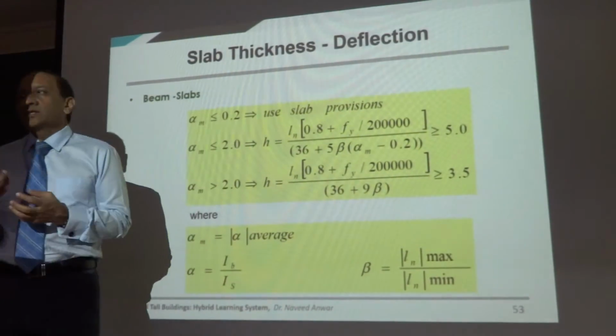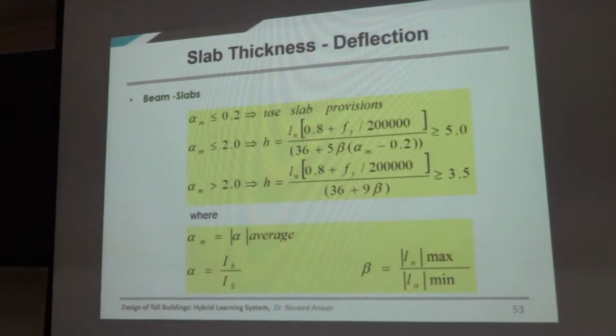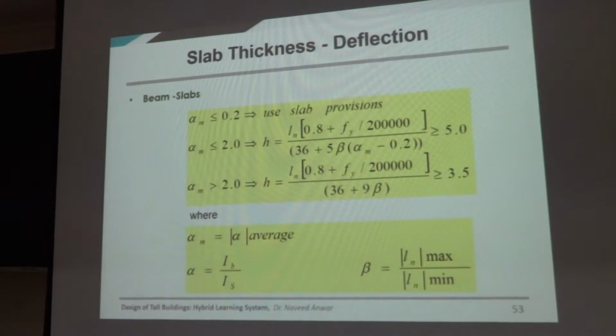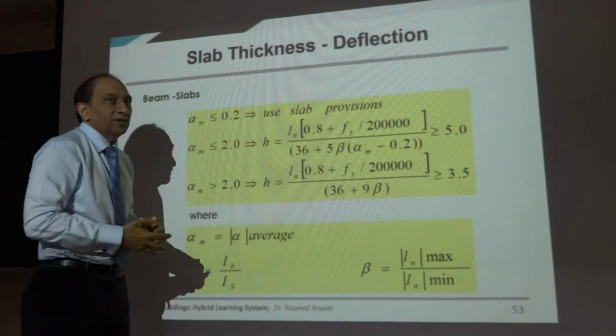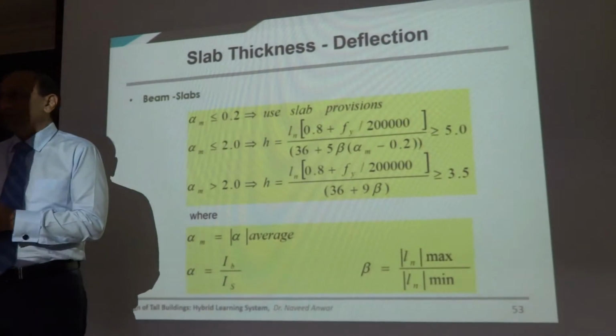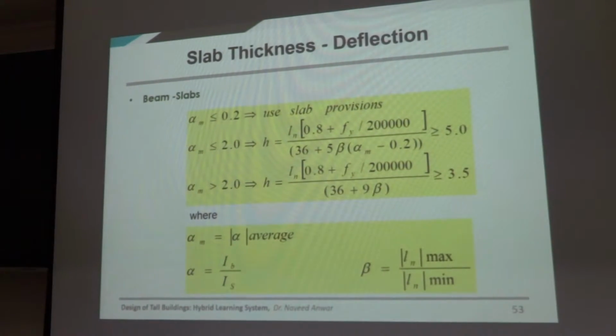But it gives you a lot of numbers, so you can check the deflection. But in reality, after all of this, we must still check the deflection calculations. But checking the deflection calculation for a flat slab system is extremely difficult. Very, very difficult to check the deflections of the slab, because it's not a beam that has only one deflection